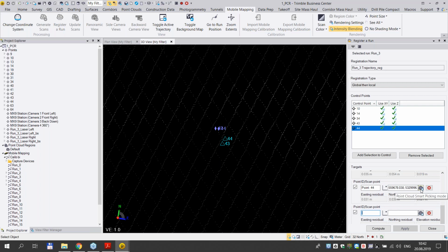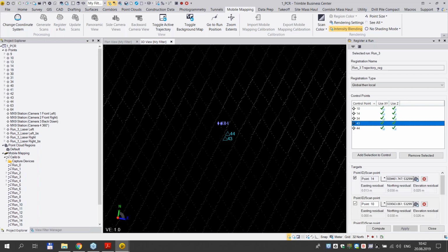One thing that I forgot to mention about the intersect plane: the intersect generate plane gives you an RMS of how accurate it was generated in terms of the information of the point cloud, meaning that a higher RMS will be generated in a ground place. Maybe you select a corner or an area where there is no flat surface.